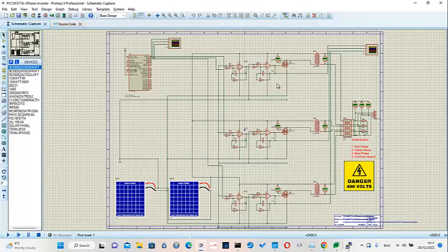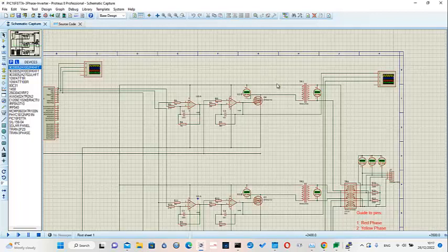So, this filtering area is there to convert the square wave from the microcontroller into a sine wave. I use two stages of filtering, and because each filter also reduces the voltage, it is a voltage divider as well as a low pass filter. I have to regenerate it using an operational amplifier.